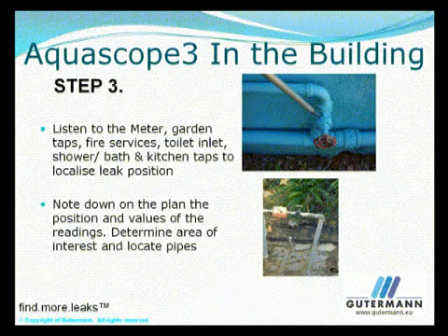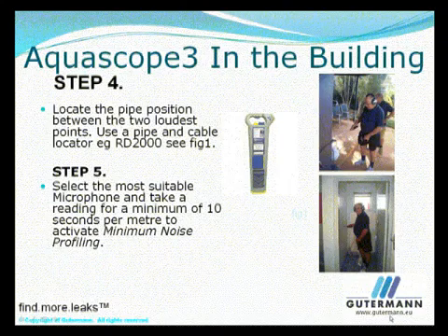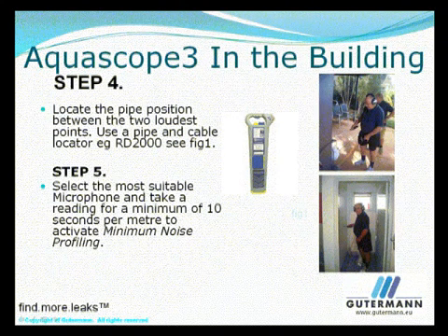Localize the leak position by taking readings for 20 seconds or more with the electronic listening stick at taps, garden taps, showers, hot water boilers, water meters, fire hydrants, and any other places the pipes are accessible. Locate the pipes between the 2 points with the loudest noise.